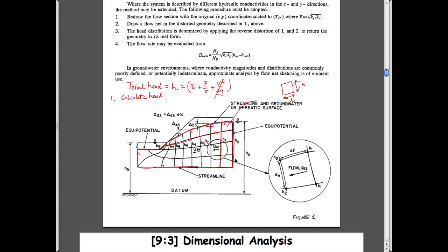So from the upstream, you could imagine that if this was just a vertical face, then you'd have the fluid pressure that would equal this amount. So the question is, why is it a constant head? Well, it's a constant head because if you take any point here, and you look at the elevation of that point, and the pressure head at that point, the sum of those two magnitudes adds up to this value of h.